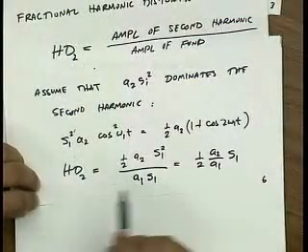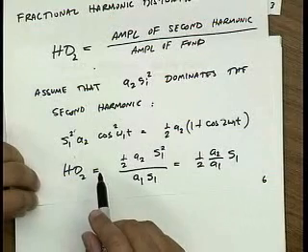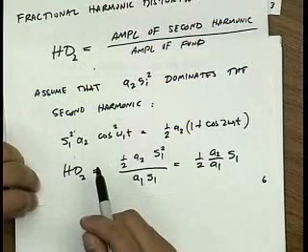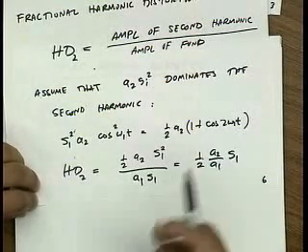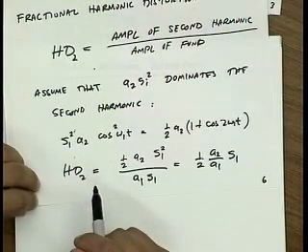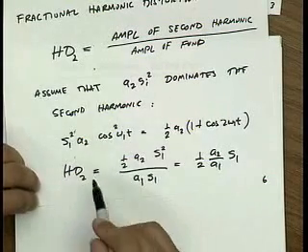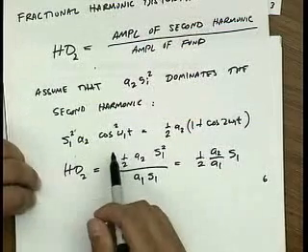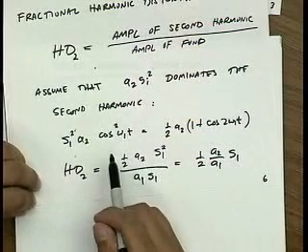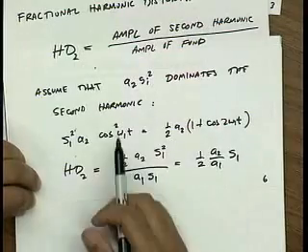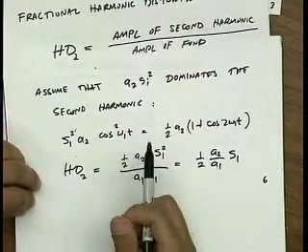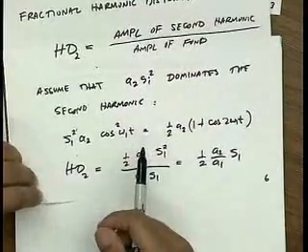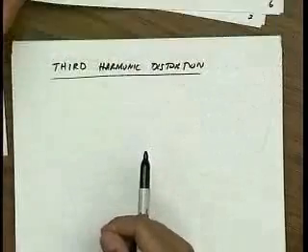Well, there's very likely, if you're watching 100 megahertz, another channel at 200 megahertz that someone's watching. So again, second harmonic matters. You might be dealing with an ultra-wideband system where second harmonic falls in band. Or something as simple as an audio amplifier, right? If the musician intended you to hear 5 kilohertz and you're outputting 10 kilohertz, again, it's not a very nice thing to do. All right.